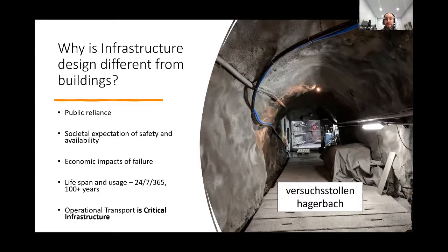So every day for the next 30 years, the contractor has 6 hours to decommission all the services, remove the rail line, drill out more of the tunnel, add in lining, recommission and reinstall the services. So they were renting a tunnel in this facility to test that process of 6 hours every day for 30 years, because of how critical it is that they don't shut down the metro system in that city.